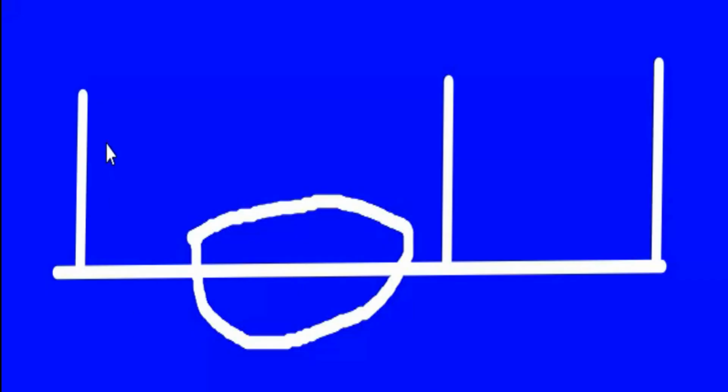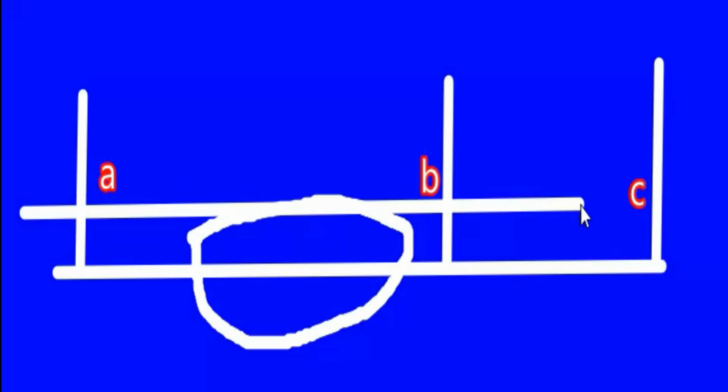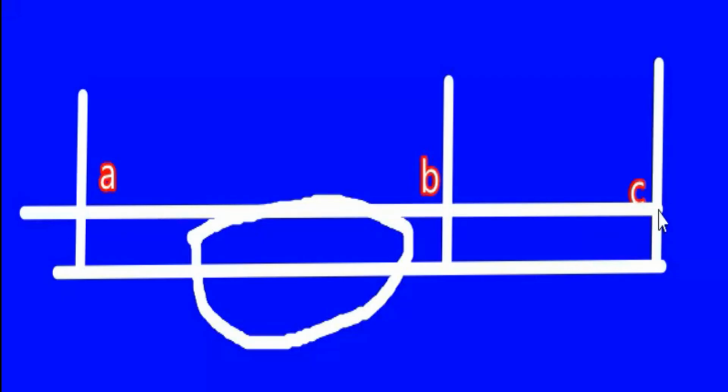So this is my A rod, this is my B rod, and this is my C rod over here. So now the ranging that we require is from this point, and we are going to range in this direction in such a way that these 3 ranging rods come in one line. So this is the first method in which the obstruction is related to the measurement.